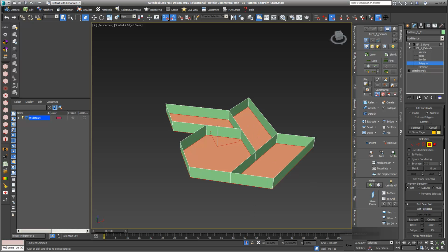And you can also just say then show end result toggle on, and you see that here this bevel comes on top. So just be aware that this has a lot of power, that it always relies on the selection. You can change this, but this can also confuse you if you just change the selections here just by mistake.